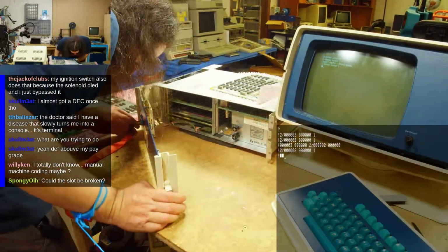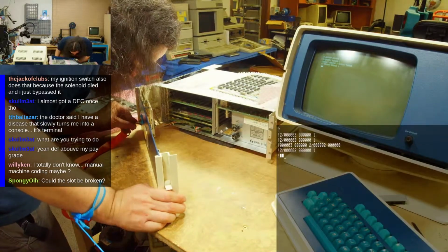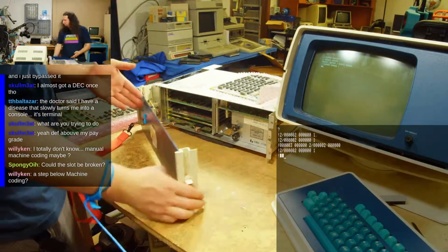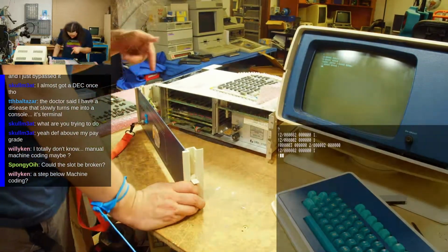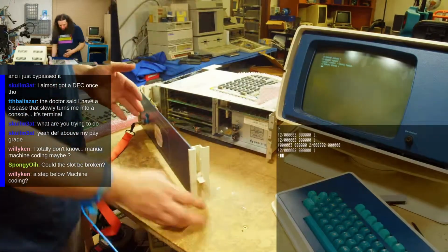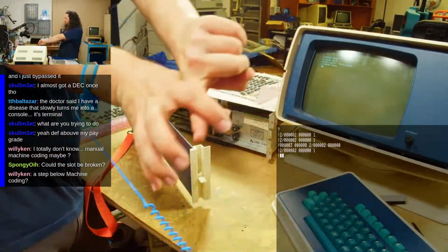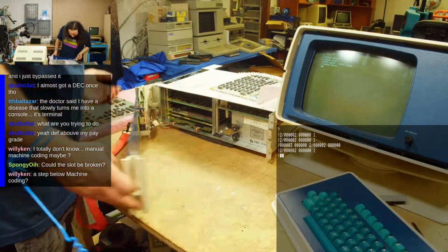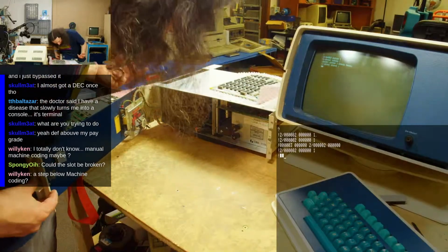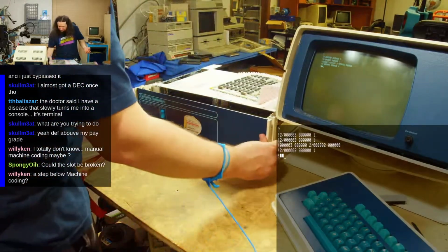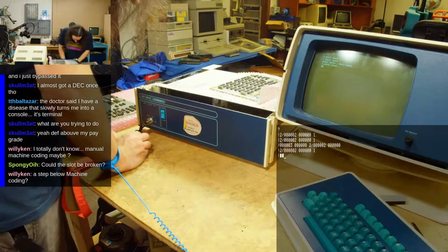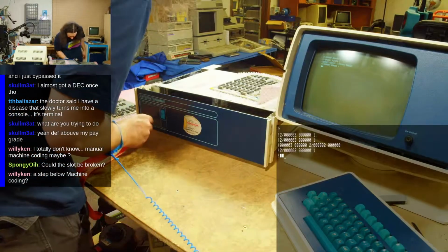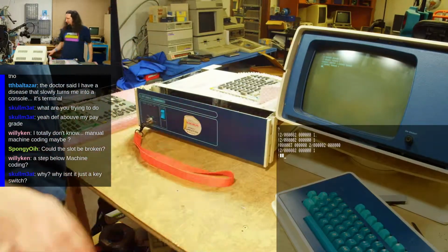What on earth? So there's a cam mounted to the shaft of this thing, and then there's 2 micro switches to the side of it, and then the cam offset lobe rotates over and turns on the micro switches. Why isn't that just part of the, like, rotator thing? That might be main power, and it needed more current carrying capability, possibly. So that might be how it just provides system power. That's super weird.